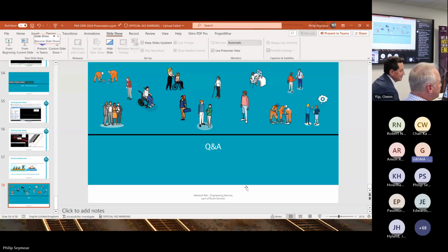Can features of the topo, such as underbridges, be dropped into the vertical to allow lifts to be managed at cut-ins, etc.? Project them in, yes. And again, we have this thing called regions in multi-profile, where it's a platform which is parallel or something cutting across the geometry plane. You can see those. Again, you could use that tracking tool analysis to see if it's 3D, if it's 2D. It is what it is. 3D have a true elevation. You can say, right, the clearance is 5.16.